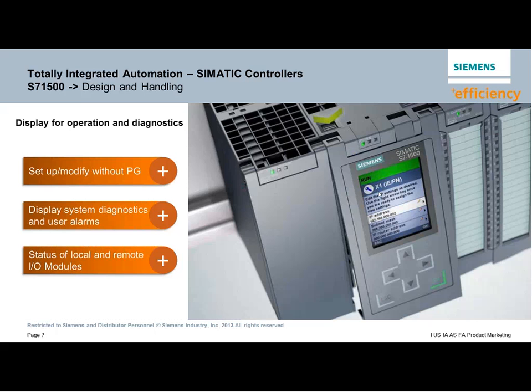We can actually see a diagnostic log of everything that's happened, and with things like intermittent faults and loose wires, it's invaluable to be able to just see time-stamped what happened, why the process went down, but now it's running and you're standing there looking at a running machine, but you know it's going to break as soon as you leave the building. So all these different features are built into the diagnostics automatically, and we just needed a way to see it.